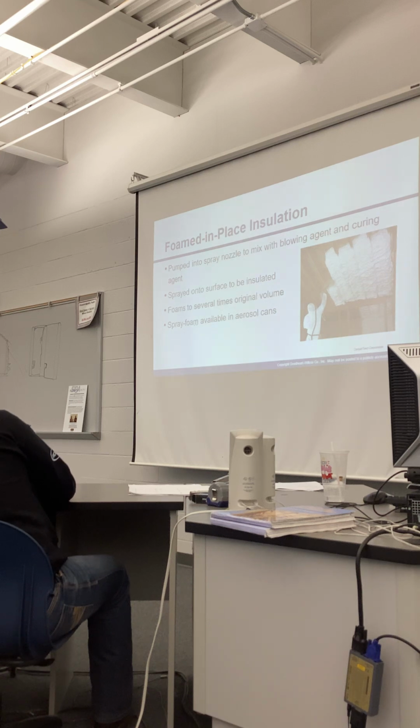So we get most of the benefit of the vapor barrier and the air sealing, and we get additional insulation. But then we put fiberglass on the inside. Fiberglass costs like 50 cents a square foot, if that, 35 cents a square foot. Instead of spending $12 a square foot, we spend $3.50.